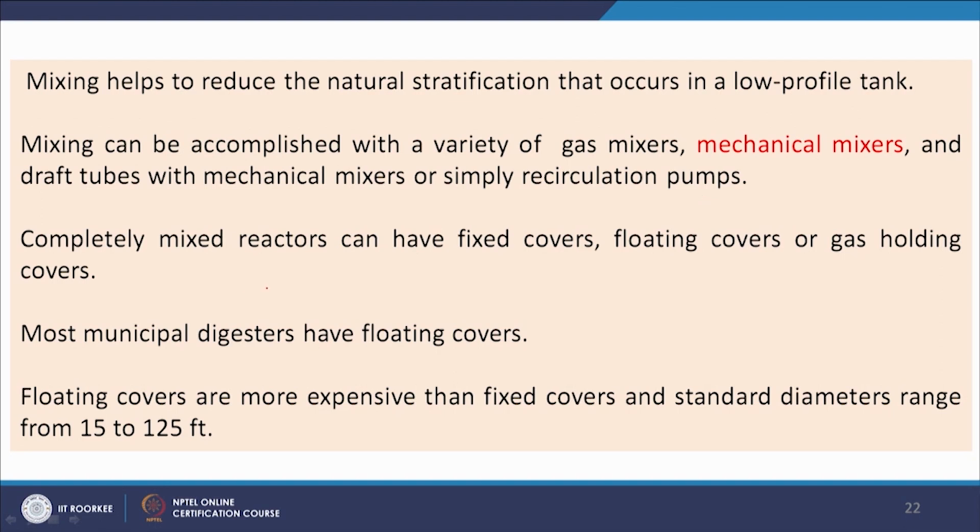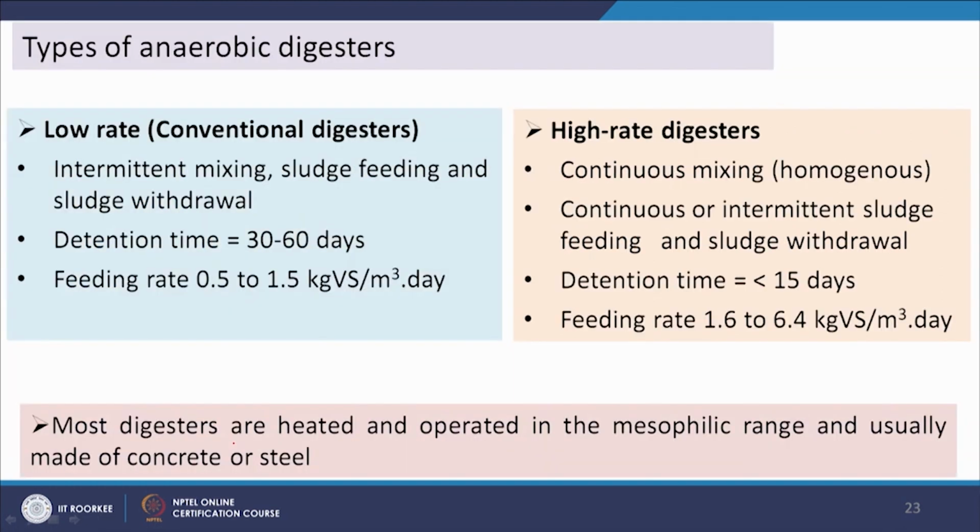And completely mixed reactors can have fixed covers, floating covers or gas holding covers. Most municipal digesters have floating covers, and floating covers are more expensive than fixed covers, and standard diameters range from 15 to 125 feet. And we can get two types of anaerobic digesters, one is low rate, another is high